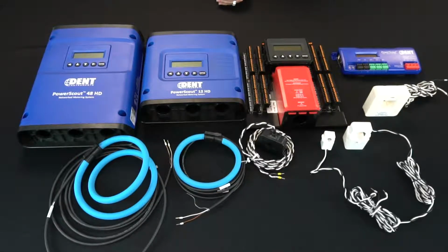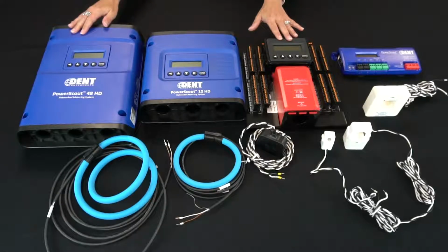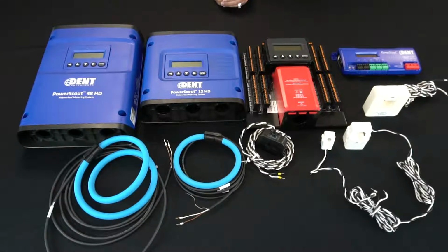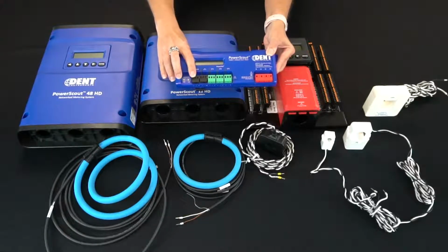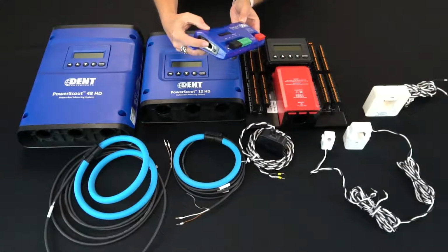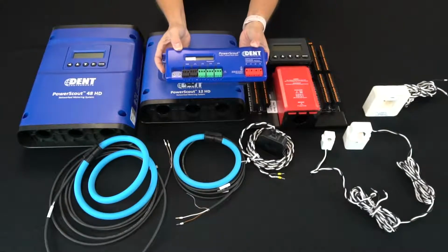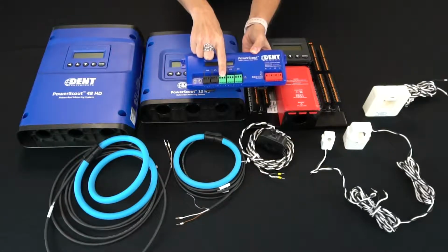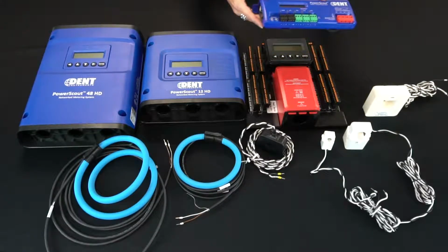Well, let's take a look, Erich. We have 3 different meters available, depending on how many circuits you need to monitor and the layout of the job that you're trying to do. We have a PS3037, PS12HD, and PS48HD, which can service 1, 12, or 48 circuits. All of them come standard with Modbus and BACnet communications, and that can be BACnet MSTP or BACnet over IP via an Ethernet port. They can be used with any single-phase, split-phase, or 3-phase circuit, and they are all revenue-grade accuracy.